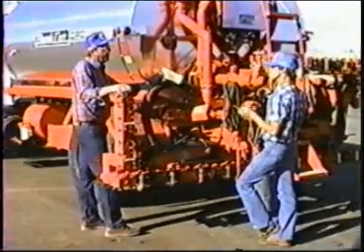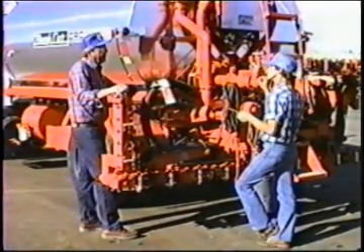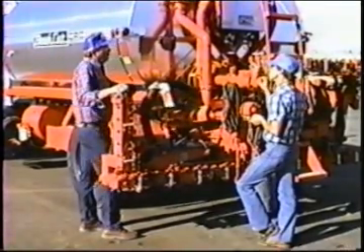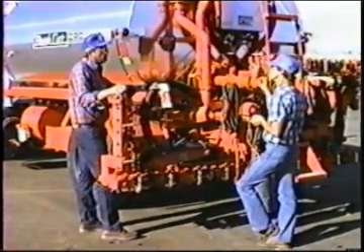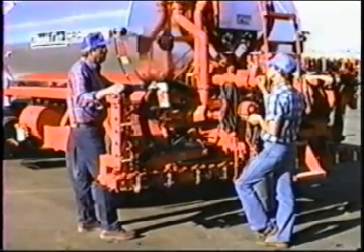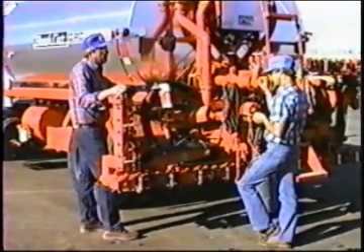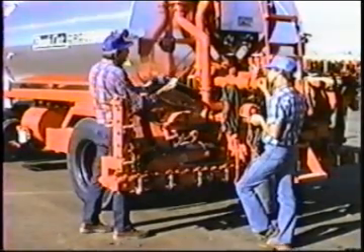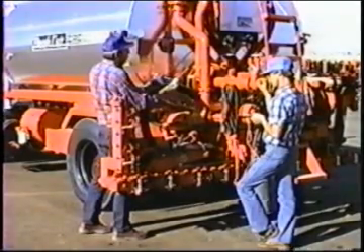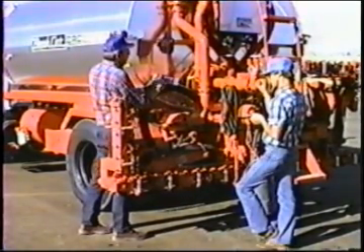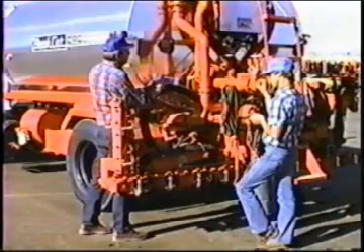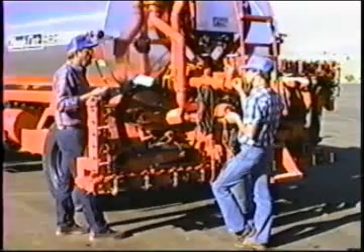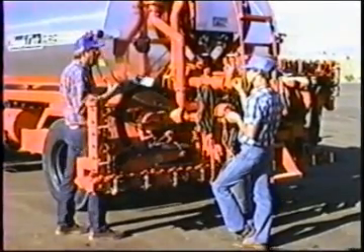If you had a mild wind, would it hurt to increase the pressure a little bit? Well, if you have a mild wind, then you have to pick the speed that looks like it's working the best. And really all you're going to do to see different pressures is to change the travel speed. You can see that at 0.25 on 400 feet per minute, a number 3 nozzle creates 8 pounds of pressure. That is, we're pushing 135 gallons a minute through that size hole, and that resistance creates 8 pounds of pressure.